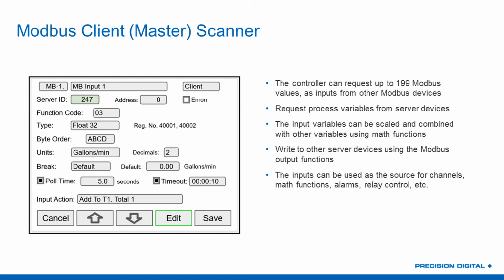And when you find it in the manual, it will tell you the data type, the byte order, the units, and how many decimal places you have. So there's not a lot of choices to make here. The vast majority of this is just looking it up in your transmitter and chugging those numbers into the screen. And because we've got a full color display here on this LCD, we don't have to deal with any segment fonts or complex programming. It spells out exactly what you want.